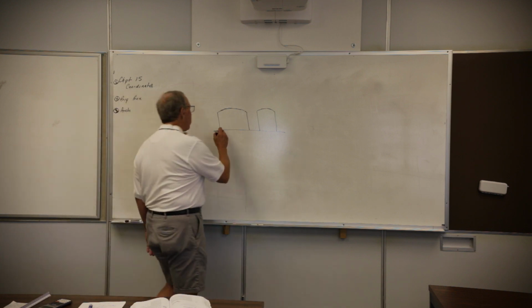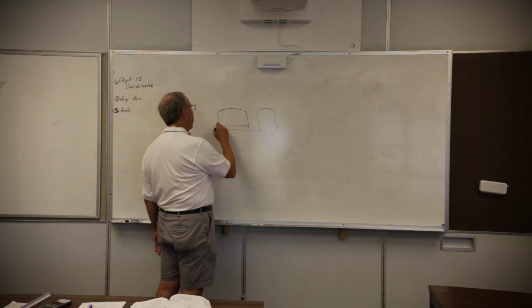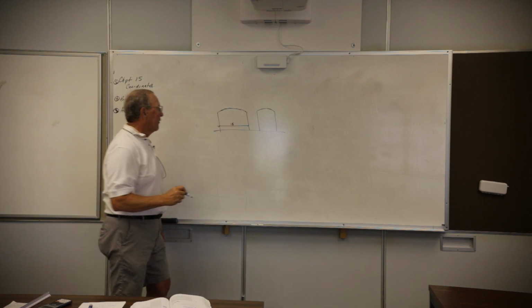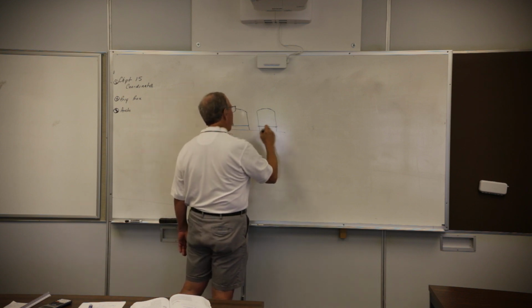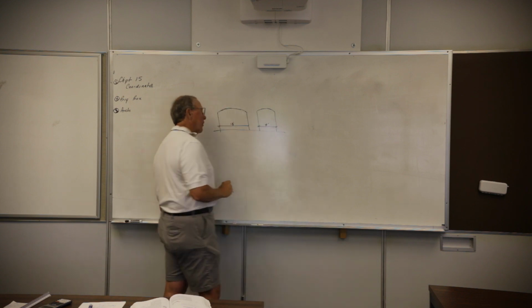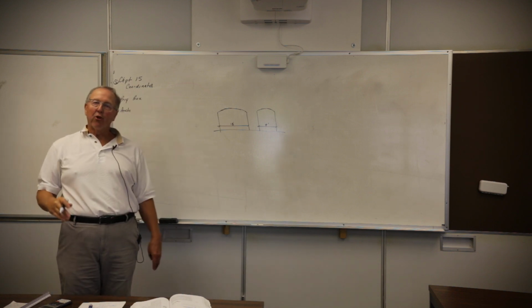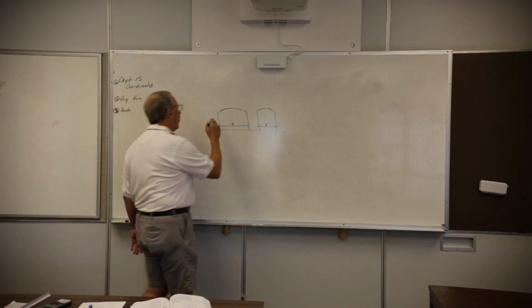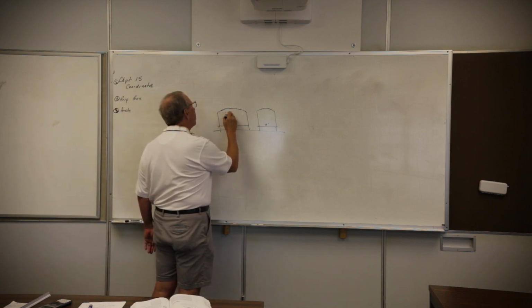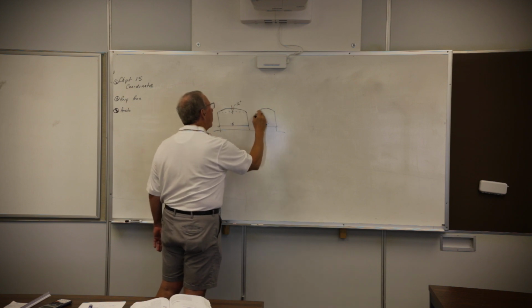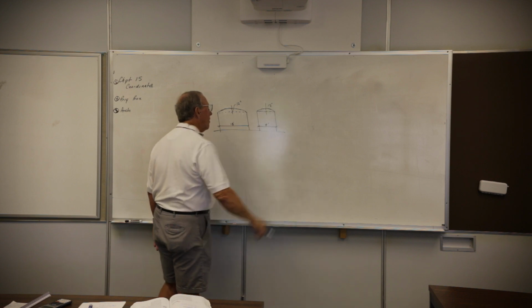Okay, to do this, I'm going to use a regular old garage door. They come in 16 and 18 footers. I'll use an 18-footer. And I'll use a 9-footer. Littler garage doors come in 8 and 9 footers. We use 2 garage doors. And let's say that we'd like that arch to be a foot tall. Okay? So if I drew a line from this corner across, and I went dead center, I'd like those arches to match in height and both of them be 12 inches tall.